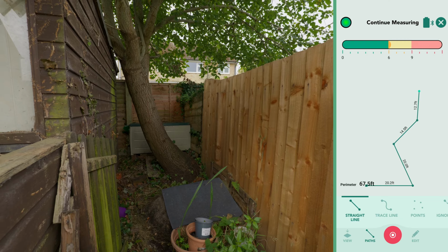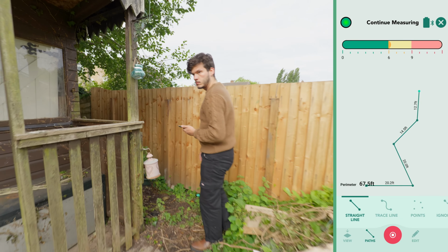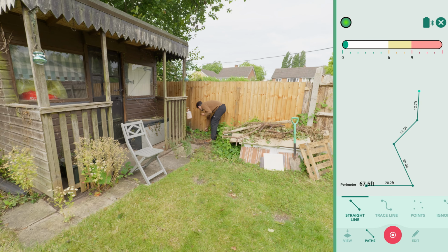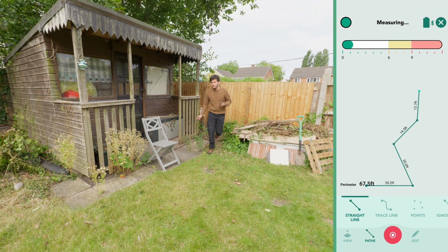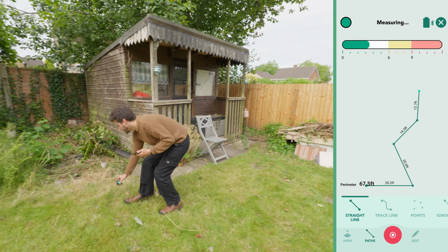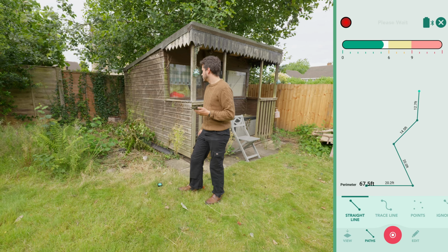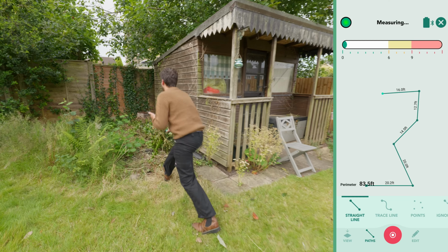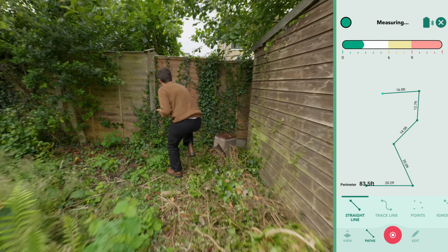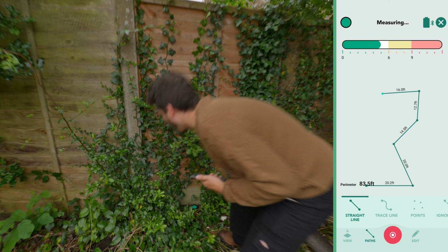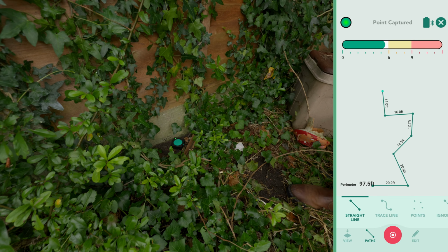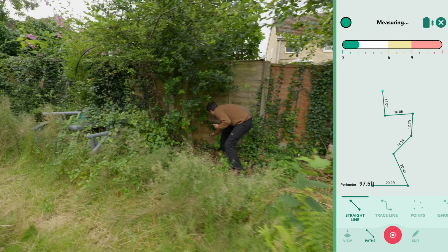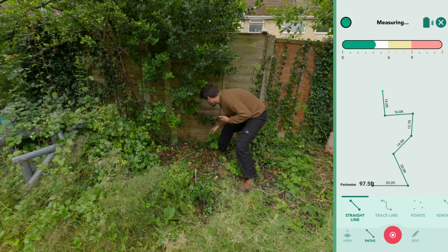As we place the Moasure device and assess our next move, instead of trying to access this corner directly, we'll use the Extrapolate Corner feature. This avoids issues when placing the device on the storage box. Instead, we'll position the device here and move around to the other wall to capture points along the straight edge. We need to capture 2 points on each wall before and after the extrapolated corner to work. Once the measurement is complete, we'll show you how to use the Extrapolate Corner tool.